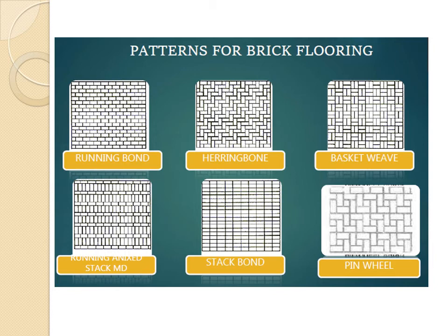So you might have studied previously the different bonds of brick. The running bond, which is like it is running in series. But if you go for the next level, you can see one brick is laid between two bricks to get the proper support. In the next image, same herringbone. Such a pattern is basically used as an interlocking system for parking areas.